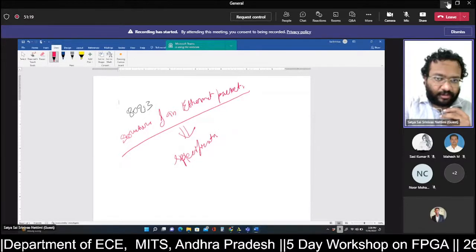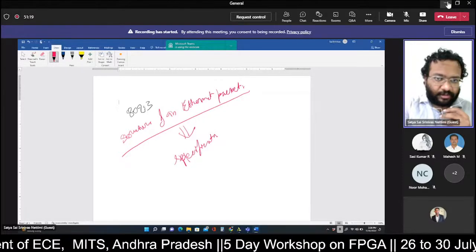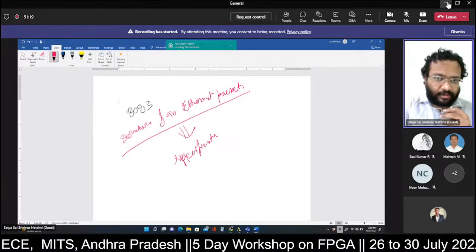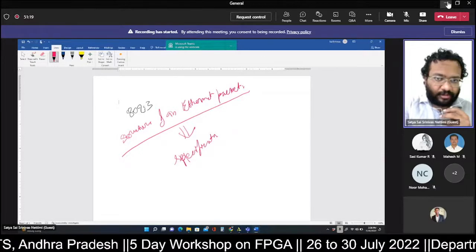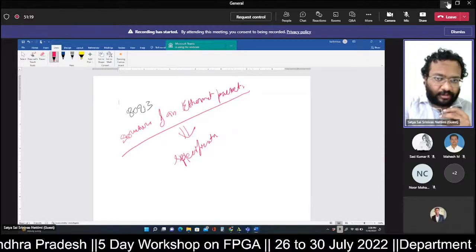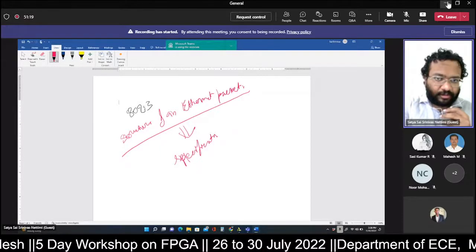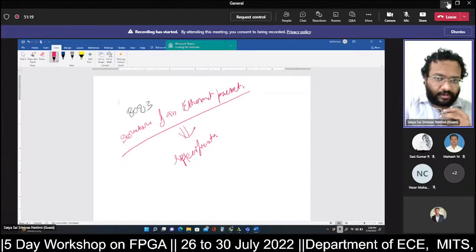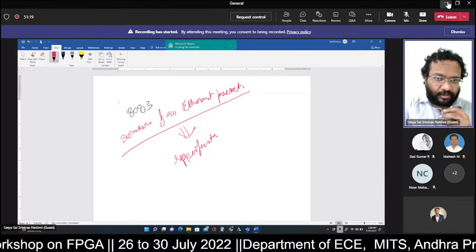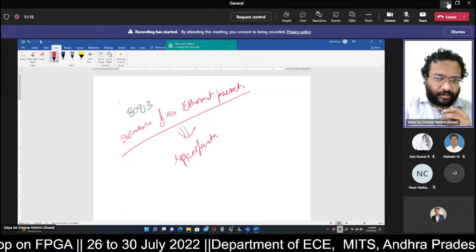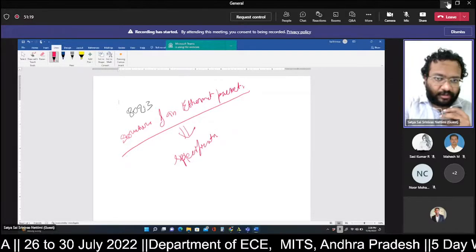Otherwise, registers will follow the next state logic. When the combinational next state logic is not performing any data manipulation operation, the next state logic will point to the register value itself. The same value is again rewritten into the register on arrival of a positive clock edge. And if any data manipulation is there, the combinational next state value will have an updated value. That updated value will go into the actual register on arrival of a positive clock edge.